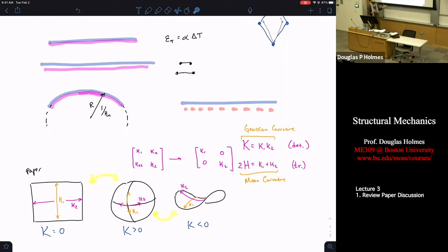So that's how your baking pan warps in the oven. It's trying to heat up into a sphere, that's too energetically costly. So instead it buckles and adopts a cylinder shape which has no Gaussian curvature, so Gauss is happy, but it has a mean curvature, so it's bent, so it's still maintaining equilibrium. It's actually bending to account for that differential heating.